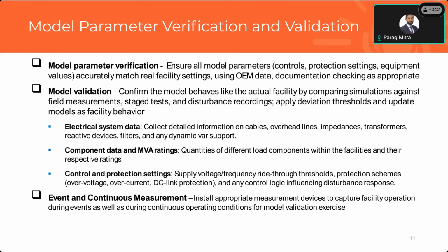Continuous measurements use devices like PMUs. You can also use SCADA, but SCADA has a very low sampling rate, so it can just be used to understand the very slow changing behaviors of the facility. But things like PMU data can be used to understand the continuous operating characteristics of the facility, and that can also be used as a data point to validate and refine the parameter tuning of a particular model. So moving to the next slide here.